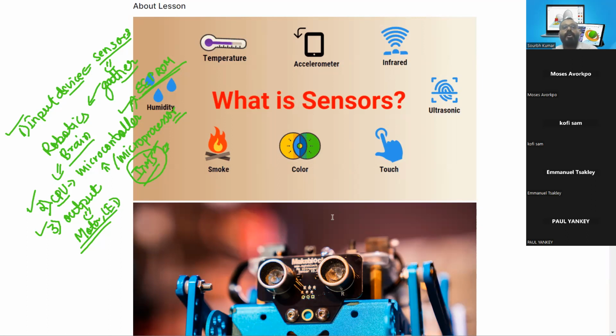So a microprocessor is only responsible for processing the data, but it requires input and output devices as well as memory, storage, and so many other things. A microcontroller, on the other hand, can store the data inside of it and also handle the execution part. For small projects, we utilize the microcontroller in total. But for bigger projects where more calculation speed is required, we utilize the microprocessor for that particular application.